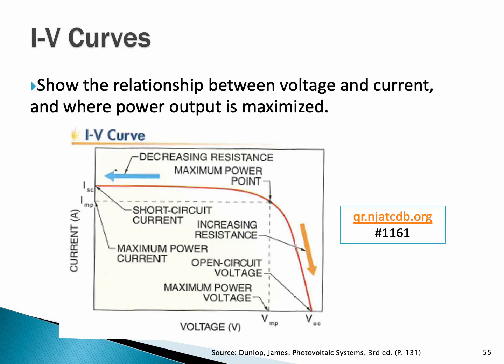But we know that we don't have ideal conditions all the time, meaning the sun is not always shining 1,000 watts per meter squared. So say we have half of that, or 500 watts per meter squared. The current line would be running across here horizontally to this point.